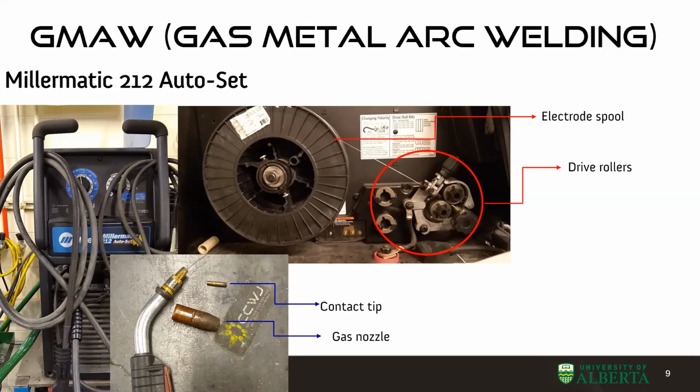But also, if you're not traveling fast, this wire is really big and comes out fairly fast, so it'll push up, and then the powder that covers it doesn't cover it as well. So it's just a start, an inconsistent stop and start. But if it was traveling before you hit the button to start feeding the wire, it would be a smoother start. Thanks. Thank you, Wesley.